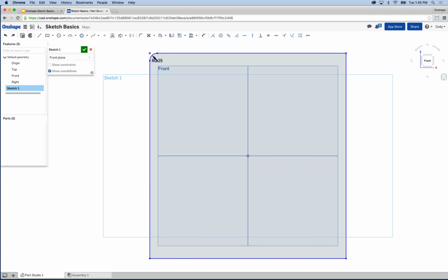But another tip, and this is just another frequently asked question: what if I don't know the size, but I just want to kind of eyeball it? I want to drag it and see what happens. You can also, instead of left clicking a point, left click and drag, and you'll get a dynamic preview of the sketch fillet. So if you get something close to right about there, let go. Okay, that's about 1.875, right?